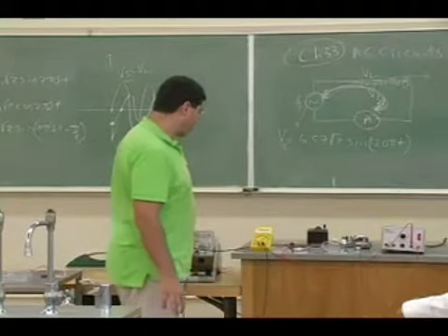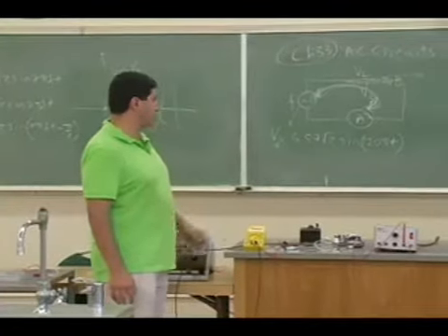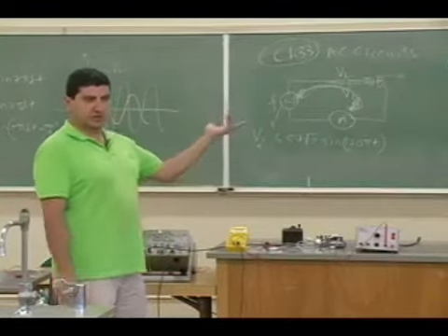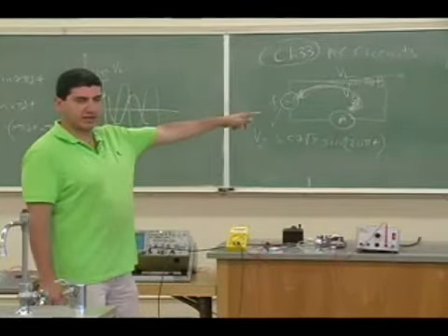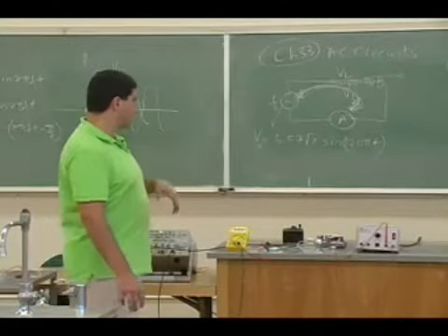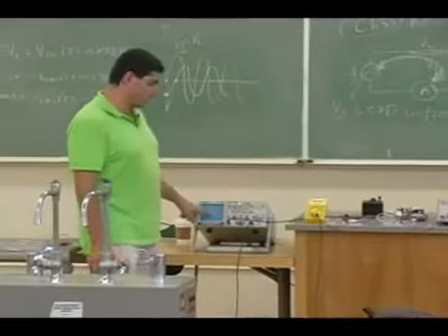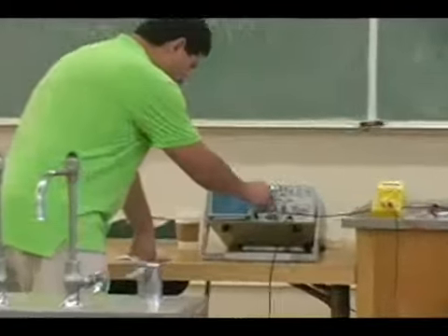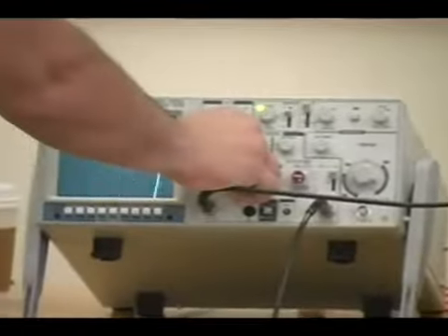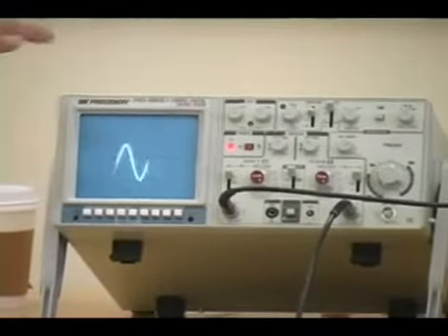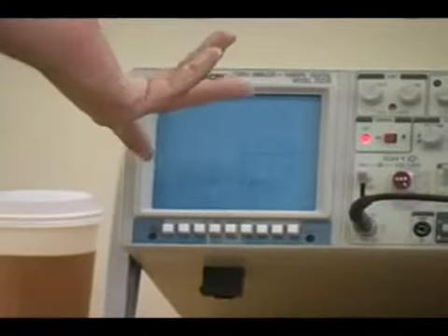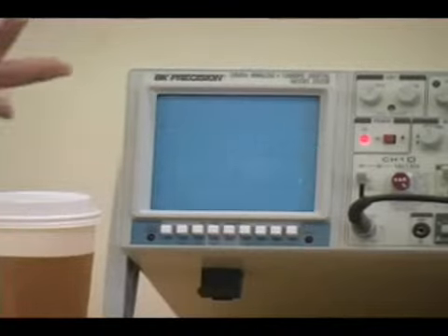The current is 0.326 amps. So it is less than the current predicted by that. Therefore, there's an internal resistance. Now, I've also got the oscilloscope hooked up across the inductor, and it should have the same voltage as the source voltage because there's nothing else in this circuit.